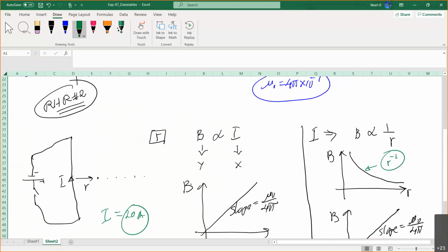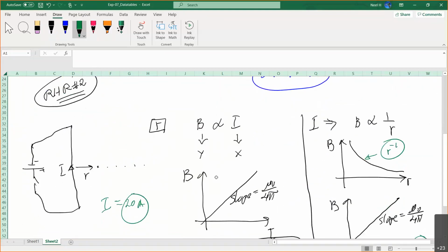The small wires can easily burn out, and it's dangerous if somebody has 20 amps going through the body. That can be a very dangerous situation. So because of that, we can't really do this kind of experiment this way in a class setting, because we have to apply very low current values, maybe less than 3 amps. That's the safe range.